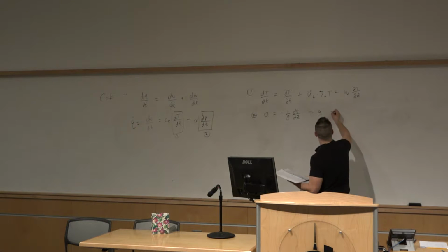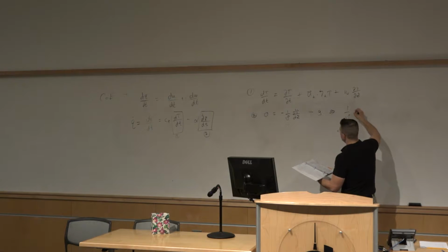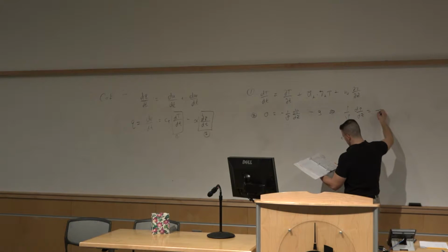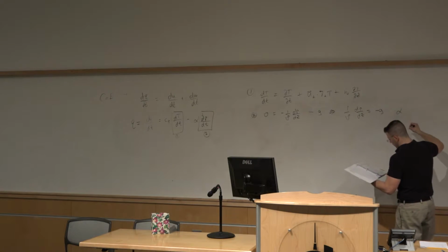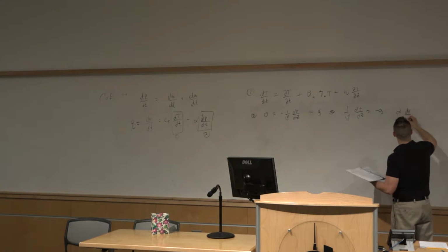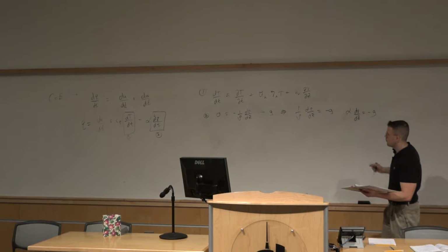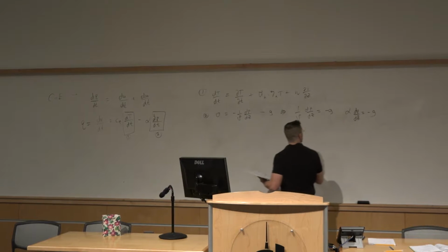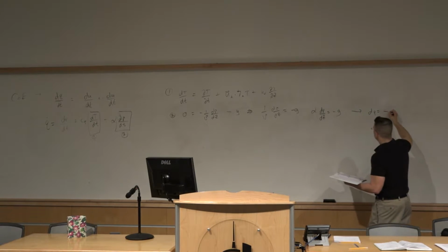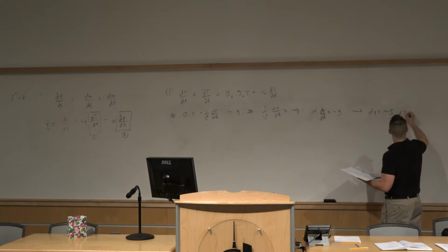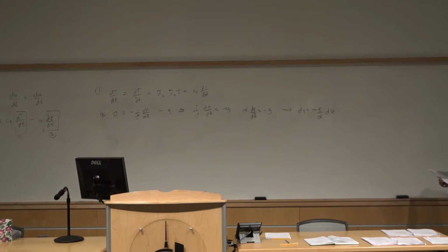And so let's express this over here, bring this to the left-hand side. 1 over rho dp dz is equal to minus g. And then we're going to express 1 over rho as alpha, or specific volume. So alpha dp dz is equal to minus g over here. And if we want to deal with a dp, let's isolate dp. So dp is equal to minus g over alpha times dz. We've just brought dz to the other side and divided both sides by alpha.